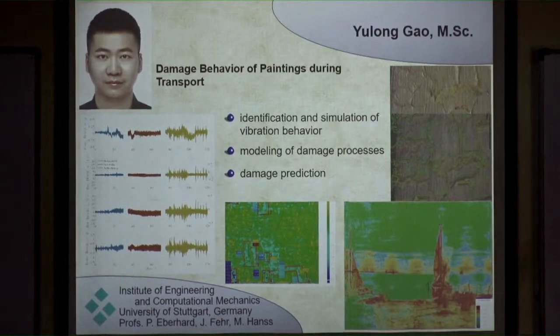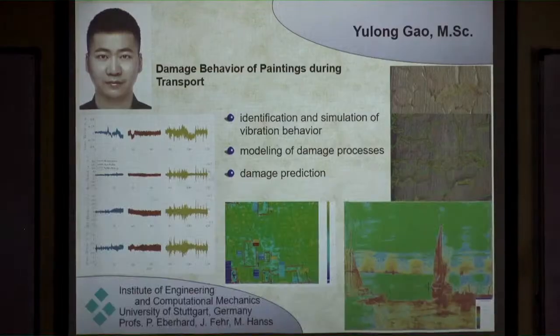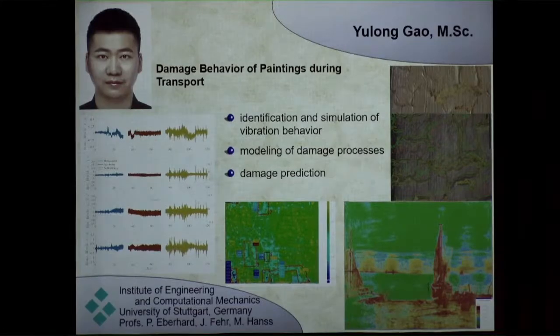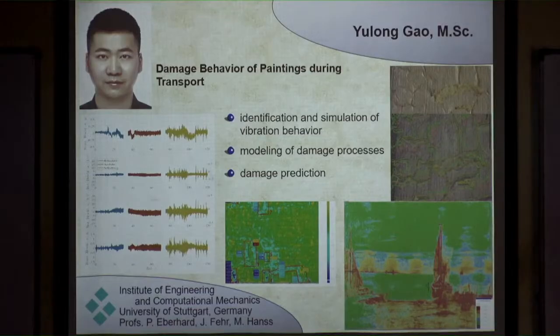So for example, when sometimes you look at such an old painting, you get the impression, oh God, this is damaged, horrible, because the paint is broken, and then the layer is sometimes moved, and so there is a certain movement like this. And so as an engineer, you first think, oh, horrible, it's broken, it's damaged, let us throw it away, or let us spend a lot of money to repair it. But this is not so critical. What is really critical, if you can see effects like this, where the paint is moving up, then you know, okay, here are now stresses and strains, and this is soon breaking up, so you have to avoid that this is breaking, because this can break and create a lot of damage. And so we have to know in such paintings what are critical situations and what are not critical situations.